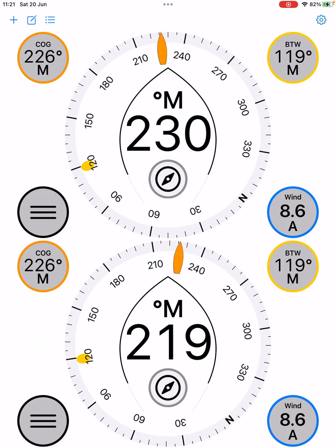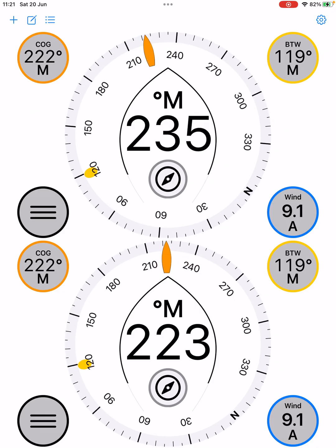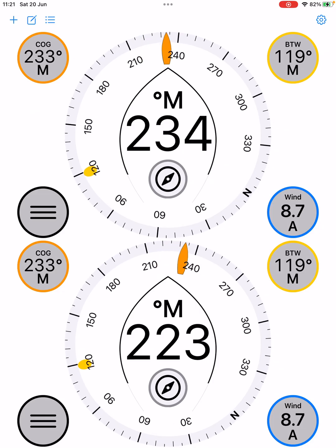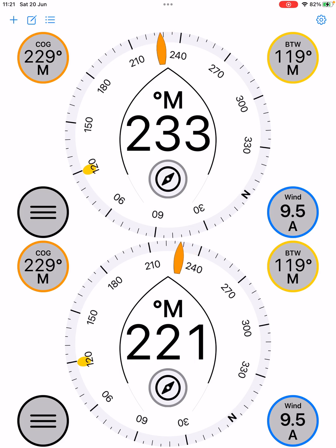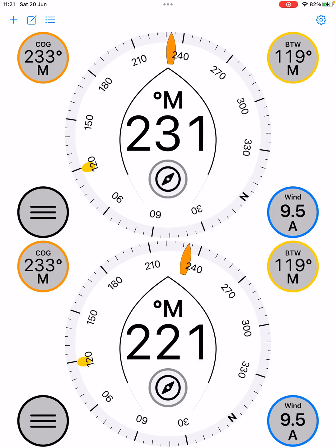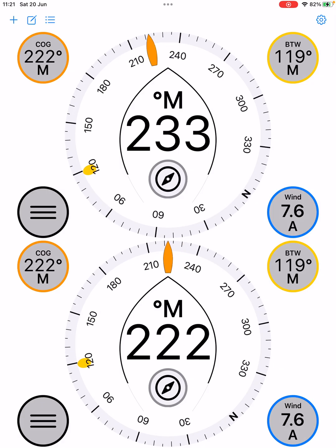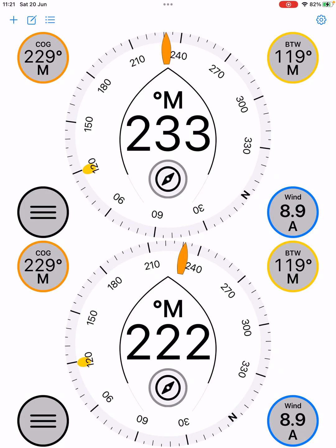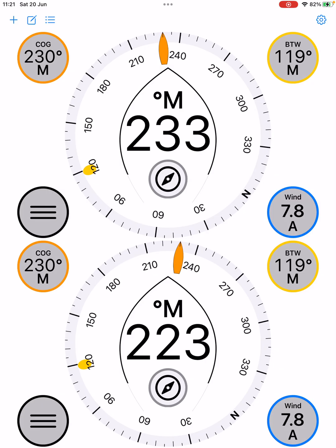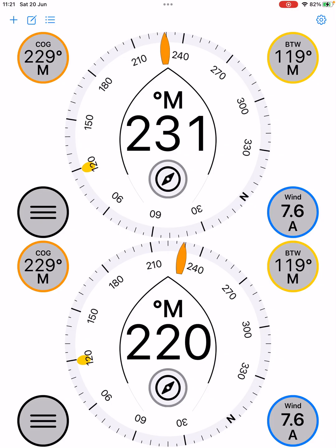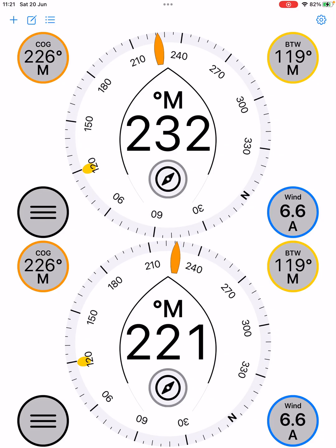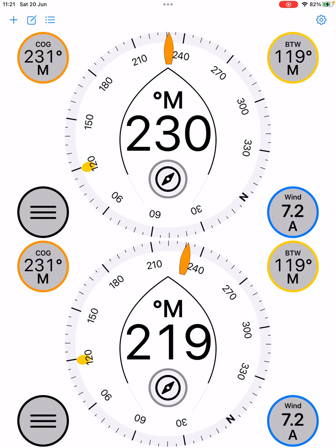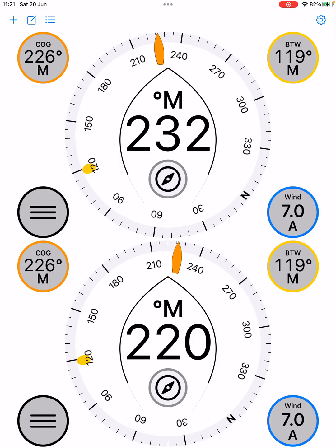which, as we know, as we selected 2 as primary and we had 2 sources, then the secondary source in this case is only one, which is the Brooks and Gatehouse compass at source 128. And we can see that they consistently differ by approximately 10 degrees, which was when both of those values were being taken as all relating to the primary compass, then that's why we had our erratic heading.